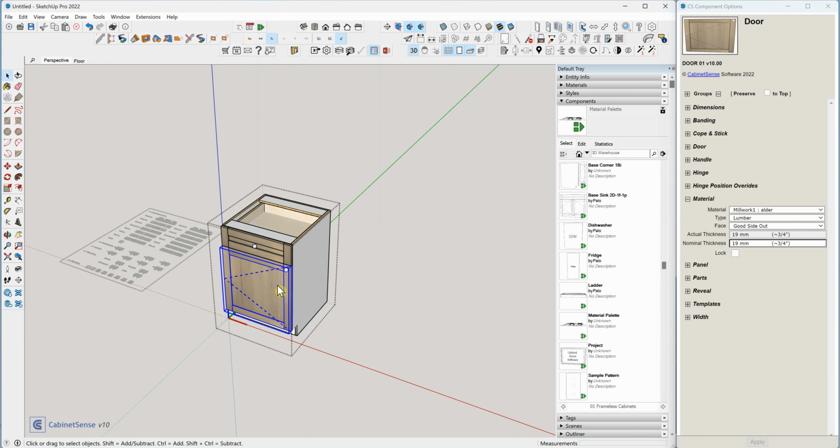We also have finishing materials that we went through, and we also have laminates. So this is where I could do something like, I want to use beige linen, and I want to use a white backer, and I'll go up to my carcass, and I will say my A side is laminate 1, and my B side is laminate 2. When I export the job, I will get the area that I need for the backer board and the area, square meters, square yards that I need for the linen.